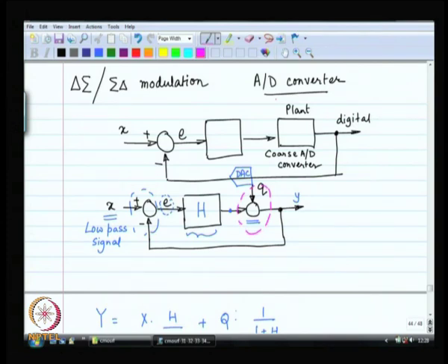In fact, in our particular case, we are going to employ a 1 bit analog to digital converter, right. And it basically introduces quantization noise. Now, this quantization noise has to go somewhere. So, that is why we made this high pass low pass business, and we said that all right, let us allow the quantization noise to go through at high frequencies, we are going to focus on the low frequencies.